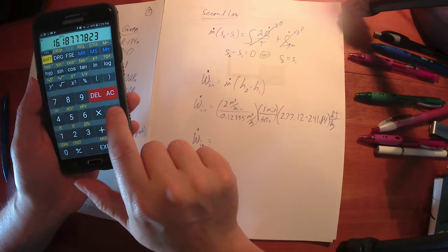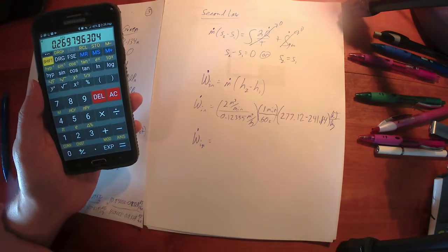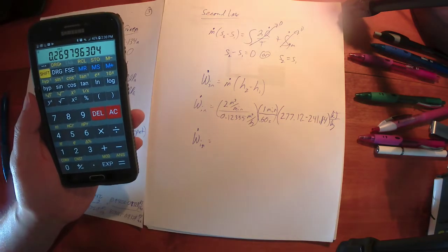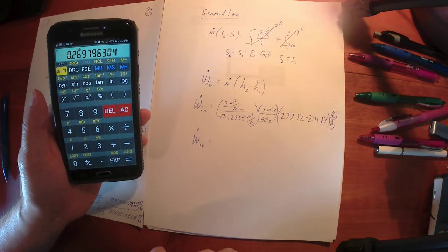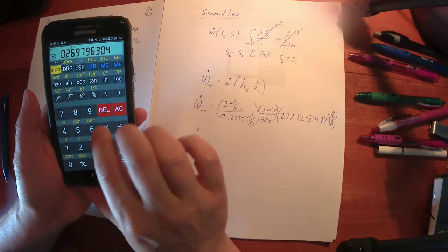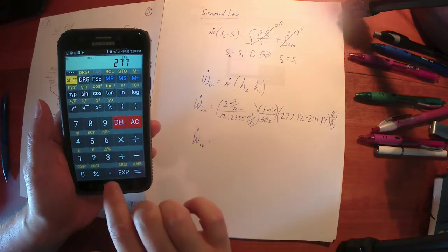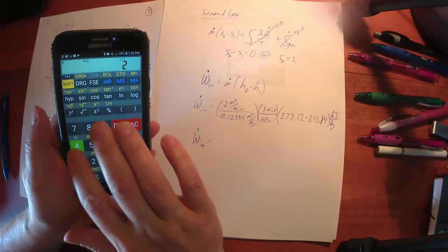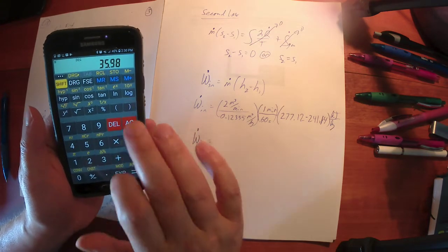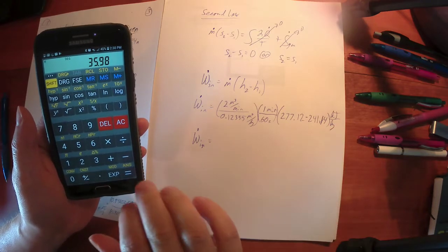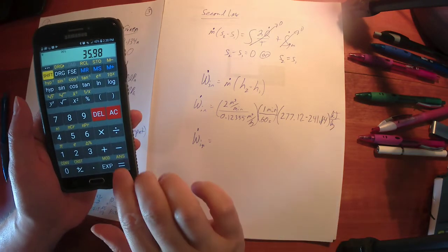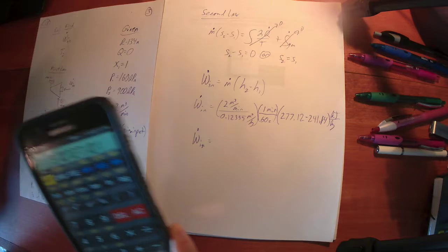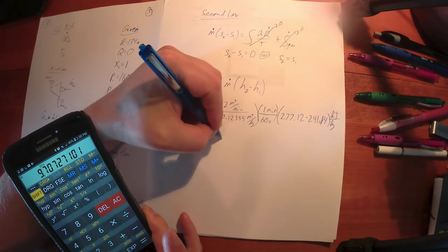So that's m dot per minute divided by 60. That should be m dot per second. All right? Oh, that's right. I got my solution over here. Yes, that is m dot per second, 0.27 kilograms per second. Multiply that by my change here of 277.12. That's my enthalpy at state 2 minus the enthalpy at state 1, 241.14. And again, those are the same units, so I just factored out the units there. So that would be the enthalpy change multiplied by m dot, and I should get about 9.7. That's what I've got there.